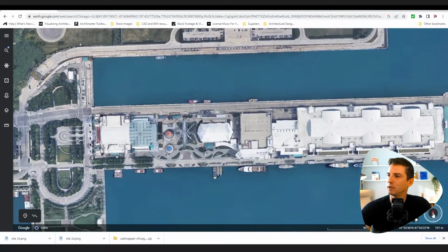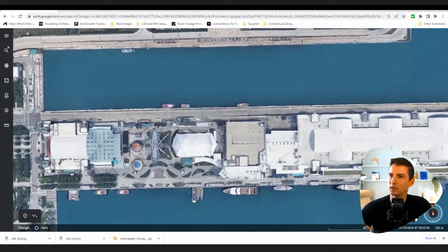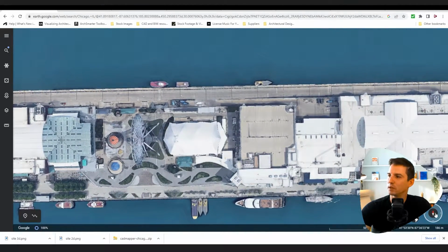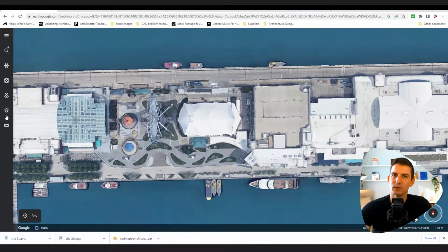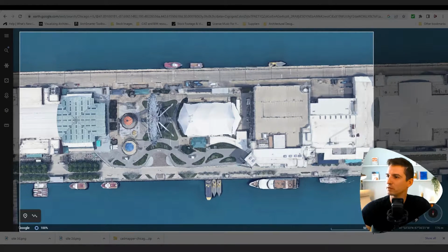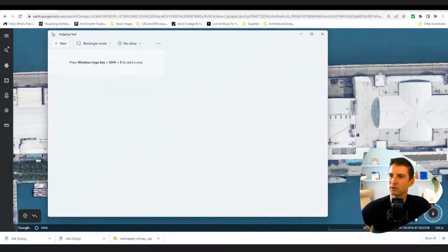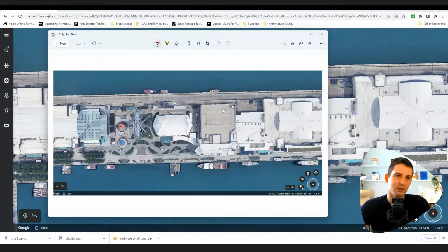So if I click on 2D, and then if you double click on the Earth or you double click on the compass, it'll then take you to that tool, and you can click and make the north arrow going up. And then we can go and take a screenshot of this, and I like to use Snipping Tool for that, which is a default program that Windows comes with. When you take your snip, sometimes it's nice to also capture the unit of measure as well as the north arrow in case you want to use this for something else. Like you can bring this image into a CAD program and then scale it based on this scale bar that's here graphically. And then knowing where the north arrow is is always handy in case you have to have a project north and a true north in your actual model.